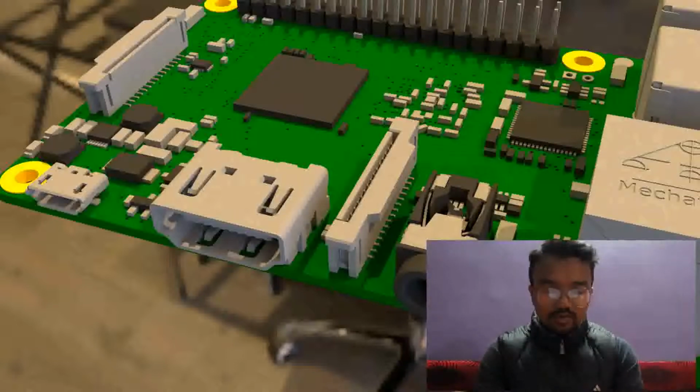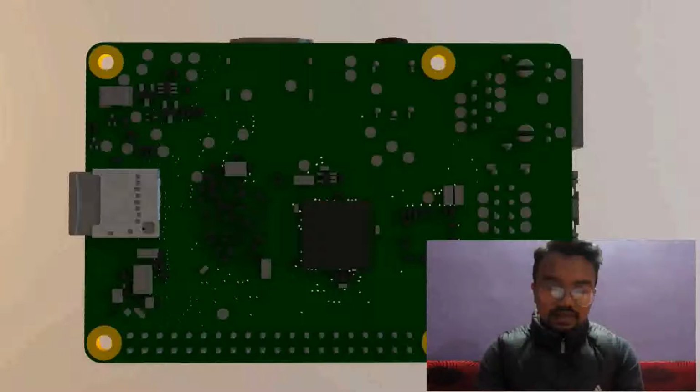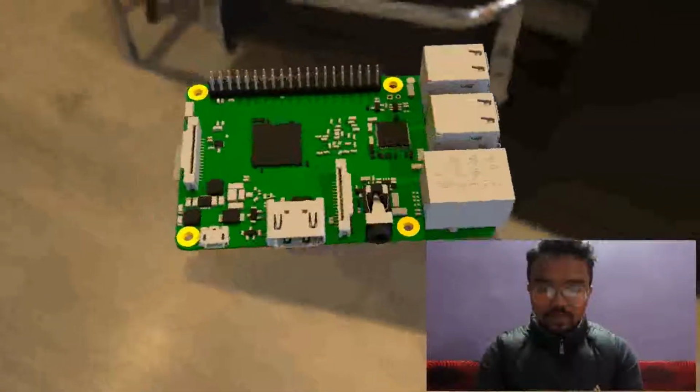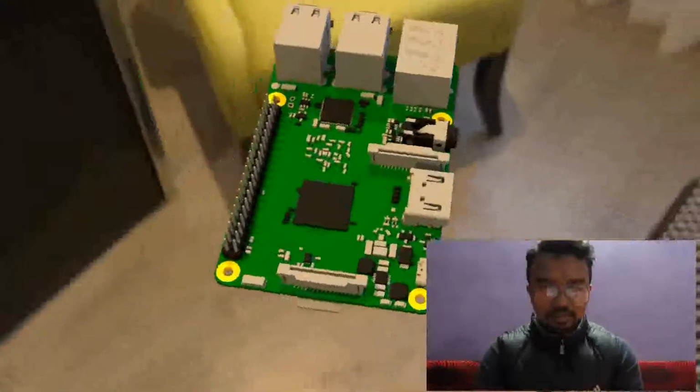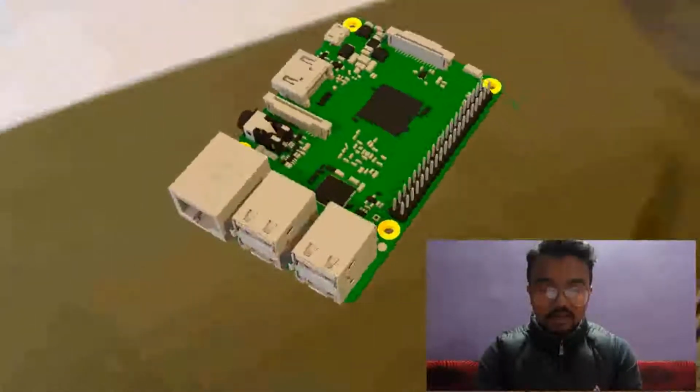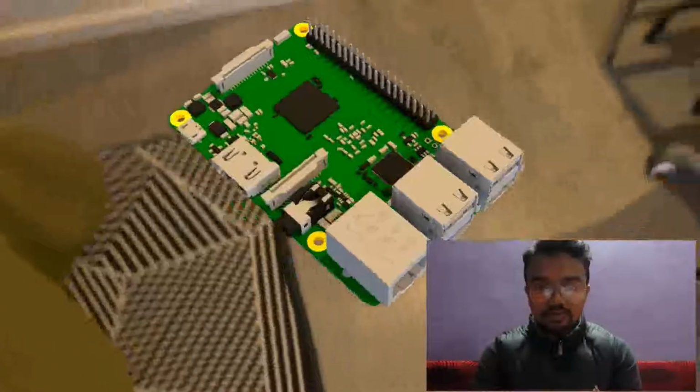Connect the mini USB cable, the power cable, to the power socket of the Raspberry Pi 3 module. Insert the SD card in the given slot. After that, turn on the power supply along with the display. Once the booting is complete, the Raspbian operating system is fully functional and can be used according to the user's demand.